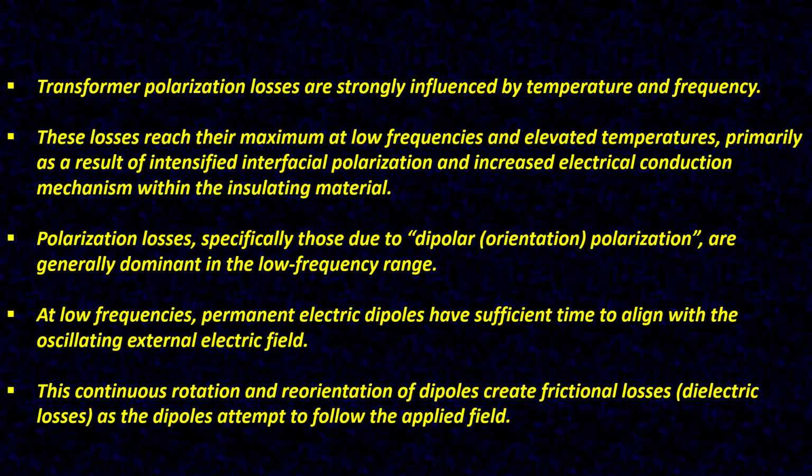Polarization losses, specifically those due to dipolar, that is orientation polarization, are generally dominant in the low frequency range. At low frequencies, permanent electric dipoles have sufficient time to align with the oscillating external electric field. This continuous rotation and reorientation of dipoles create frictional losses, that is dielectric losses, as the dipoles attempt to follow the applied field.